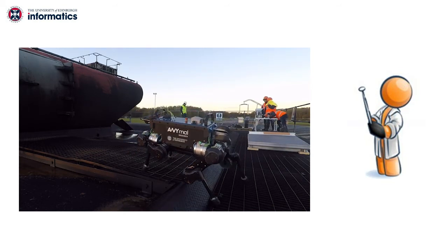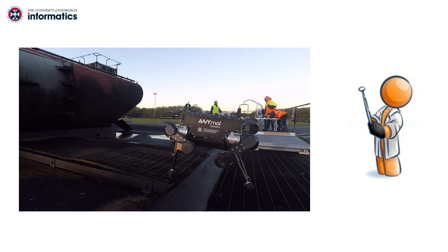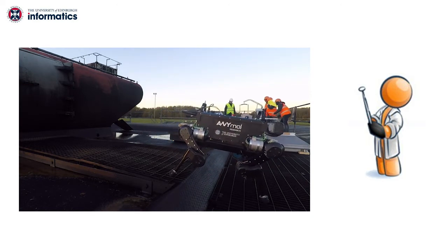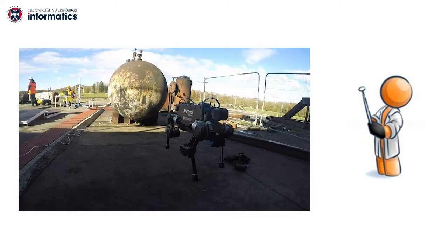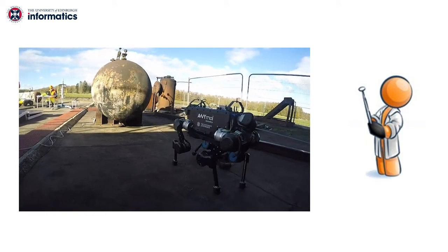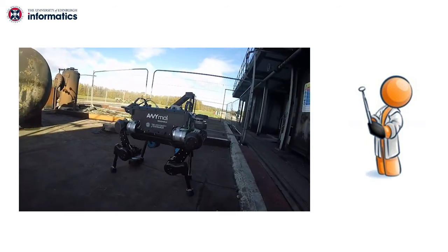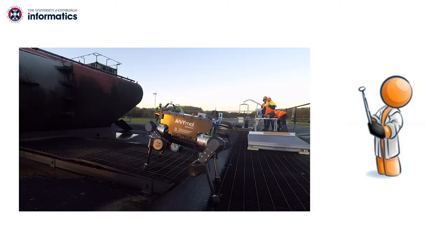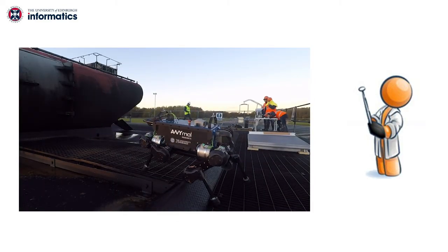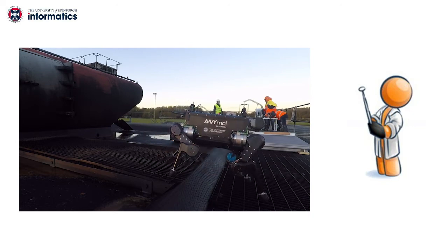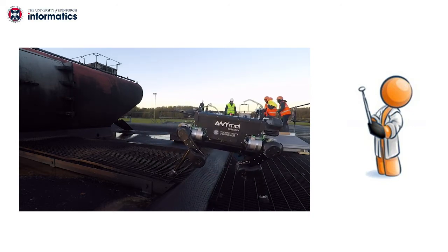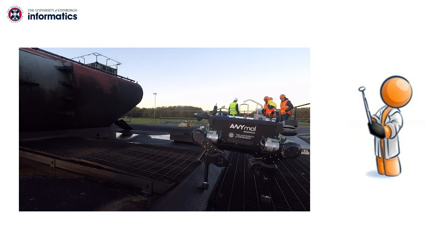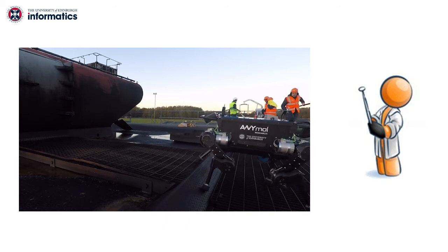For instance, the video shows a field trial of our animal robot, where a human operator is supervising the gait pattern selection. When moving on the flat ground, the human operator chooses the trotting gait to achieve fast locomotion speed. When there are terrain irregularities, a more conservative gait pattern, static walking, is selected to increase robustness. However, relying on a human for gait pattern selection can be tedious and difficult.